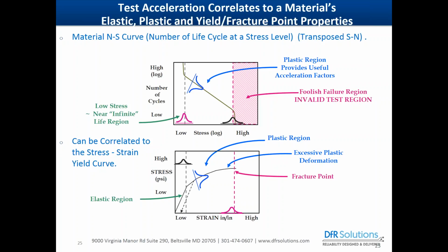So that can be considered that the name highly accelerated life test that Dr. Hobbs gave to this procedure isn't really the best name for it. I would prefer to call it a product ruggedization development process, because it tells you what stress levels you will break the product on. And yes, a stronger product will also have a longer wear-out or aging life, but you don't know how long until you correlate it and keep it within the wear-out range and don't go into the yield fracture point.